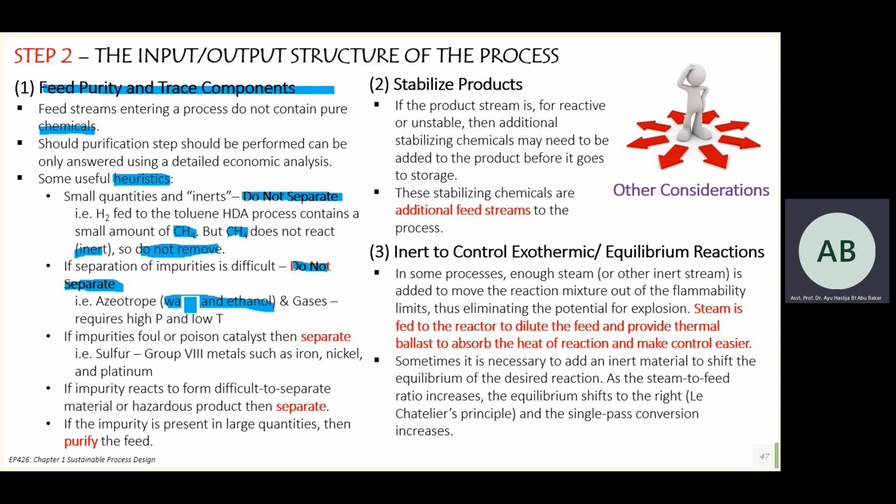Yes, the boiling point is too close. Water is 100, ethanol is roughly 70 to 80, right? So the boiling points are quite close, so it is hard to separate. If you do the separation, you will perhaps require multi-stage distillation, a few steps of equipment. Okay.